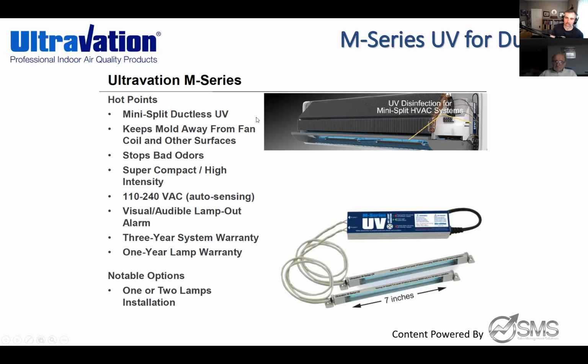So these things become science experiments. I've seen some pretty bad, filthy ductless heads, especially in restaurants, places that work with yeast, like pizzerias, bars that have beer, the yeast from the beer. Man, stuff can really grow inside these heads. So we highly recommend that people do have these on a cleaning contract, and then you would change these bulbs annually if you have this kit installed on the ductless head.